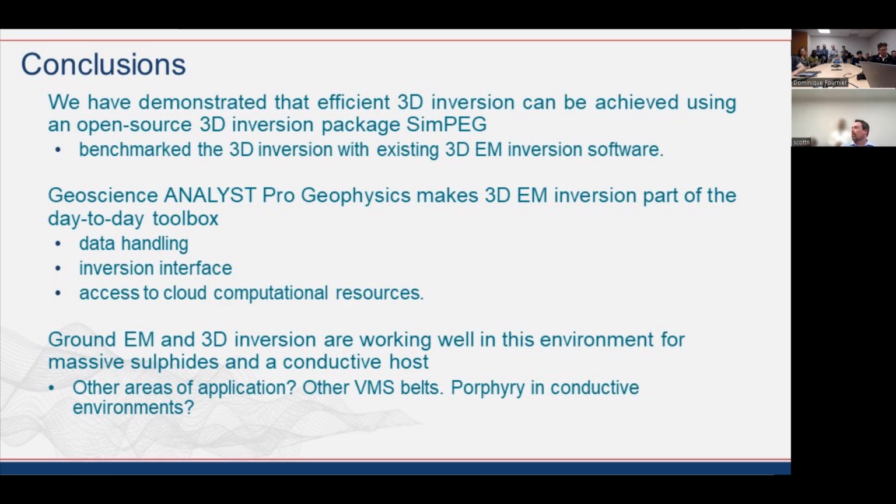So overlapping loops, is that over continuous loops like we have? Yeah. Our coverage in this survey was typically, although there were a few lines right where this thing was, where we extended outside the loop 1 kilometer, inside the loop 1 kilometer, and then outside the other side. And we moved the loop and surveyed the same thing all the way through. If you had continuous coverage like that, you would see everything from every different angle. That's the stepwise loop, but also surveying inside the loop.